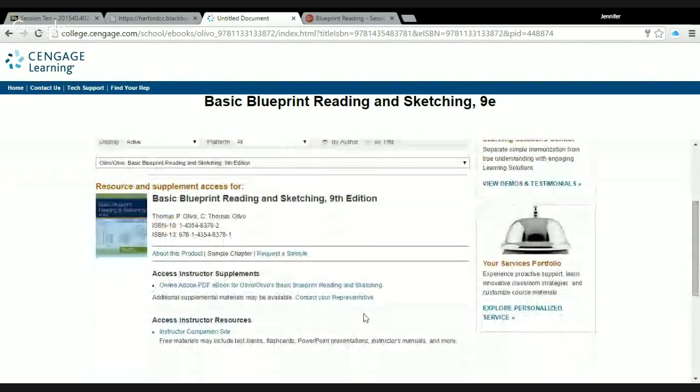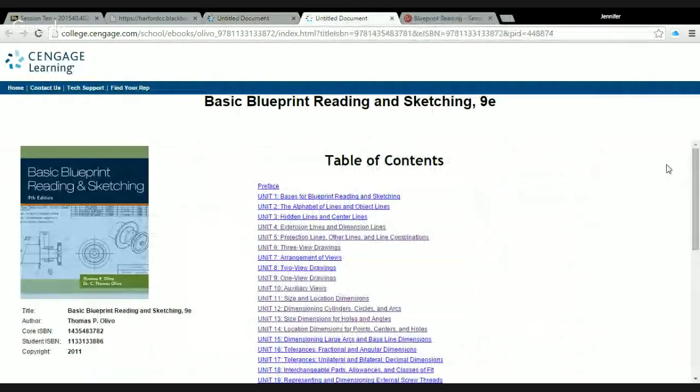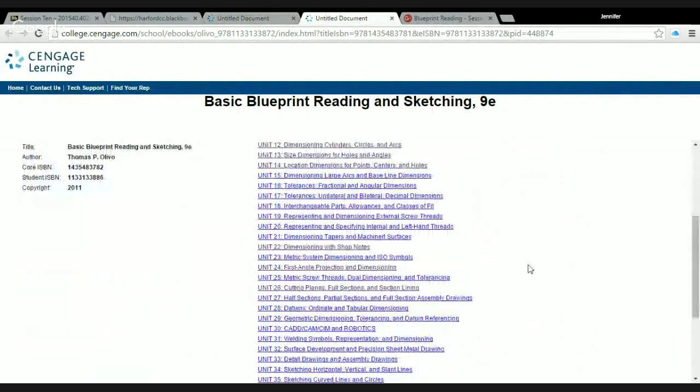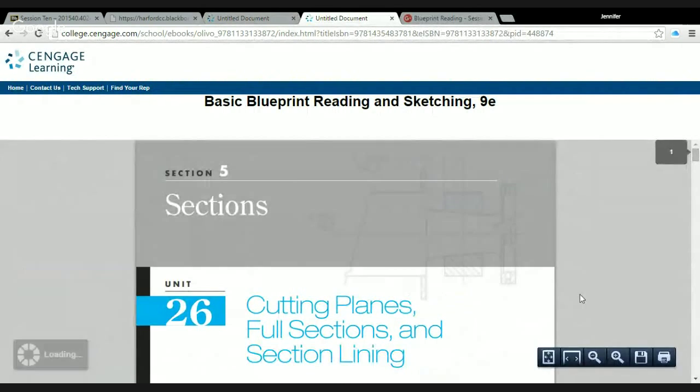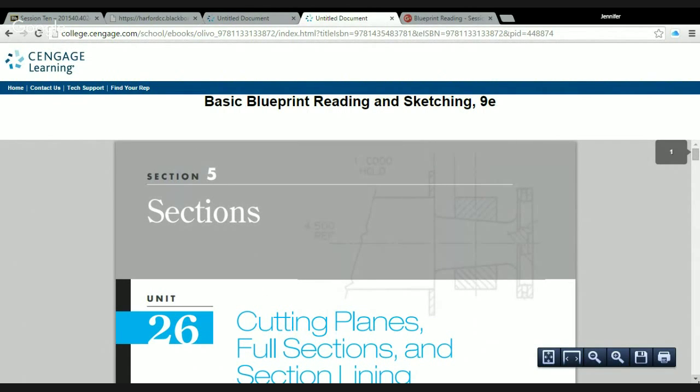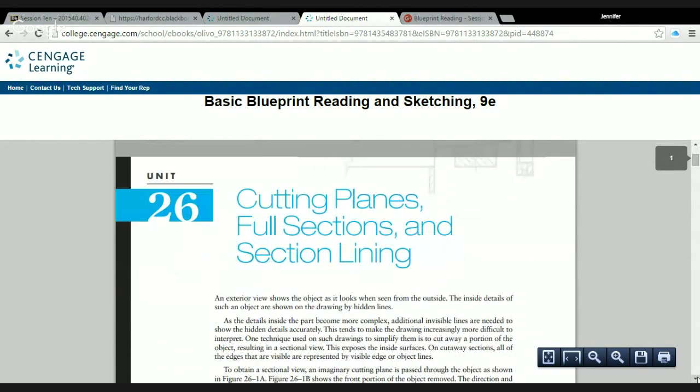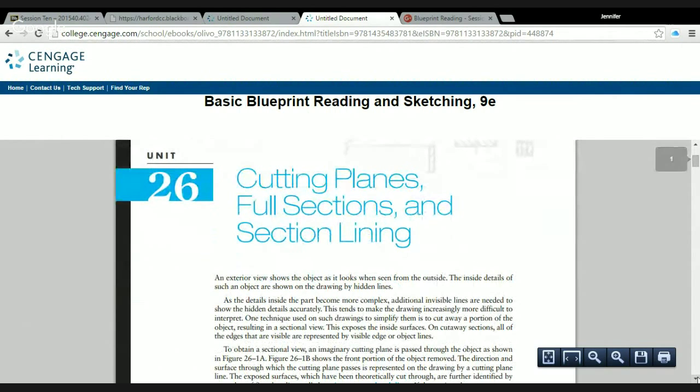Okay, so section views. We've looked at briefly what a section view is, but we got to get familiar with some of the terminology and exactly how these things work, so that if you come across them on a drawing somewhere, you know what you're looking at. Basically, section views, as we've got listed here in our outline, are obtained by cutting through a part or parts using an imaginary plane, typically to show the inner features more cleanly than through the use of hidden lines.